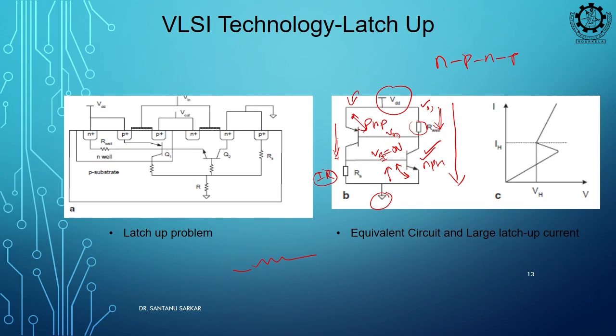So, it is like a positive feedback. It will keep on growing, and what will happen at the end? So large a current will flow that the structure will break because of higher melting or temperature, or destruction. Okay. So, that was a problem in the CMOS circuit, earlier CMOS at the beginning. Now, technology is quite matured and generally we do not see this problem.